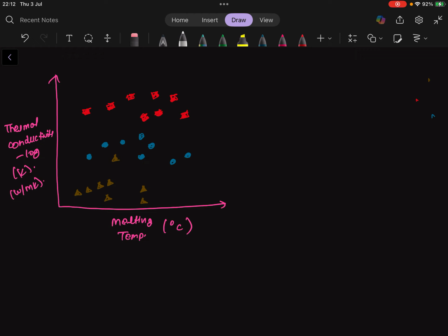So basically, in the plot, we had different classes of the PCM material with their range of heat of fusion. We can notice that the organic material has quite low melting temperature as they are polymers but have high heat of fusion. For organic materials, we have heat of fusion around 200 to 220 kilojoule per kg.